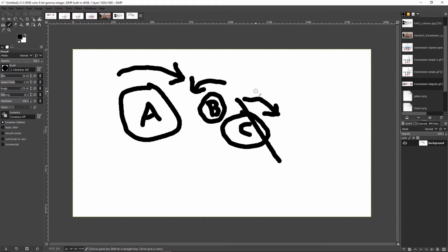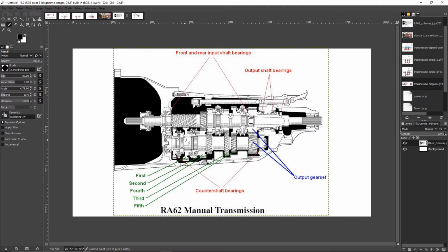No C. So if this was second gear, B right here, if this gear set achieves second gear, and I eliminate the counter shaft on C, now my output is reverse, equal to whatever second gear is. So if you've been playing around in reverse, and reverse normally doesn't achieve a very high top speed, it's because it's normally first or second gear in order to make this compound gear set simpler. So I thought that was cool.